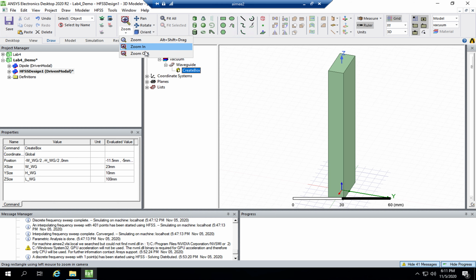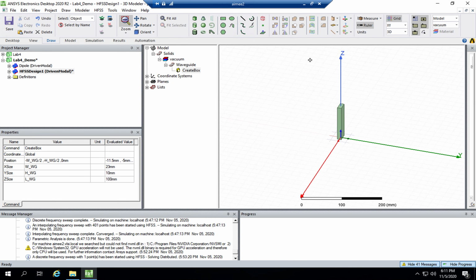So I'm just going to create another surface on the top here, which is at the location where the horn is going to end, and that surface would have the same final dimensions as the horn. And then I'm going to connect the two surfaces to create the object, which is going to be the horn. So if you follow along, you'll see what I mean in a second.